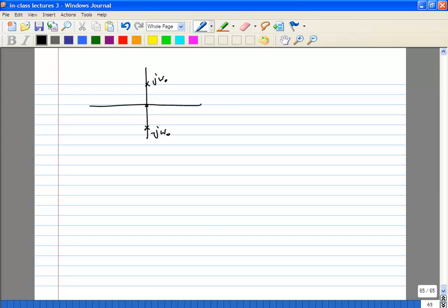So what happens is, initially the poles start off somewhere here in these two places, right? One of them is a capacitor, other is an inductor. Eventually they will move somewhere here. And you will see them splitting at some frequency. Actually, this is your Q equals half point. That is a point where, if you take your discriminant, root of b square minus 4ac, you will find that at that point it goes negative, and you can get this condition Q equals half from there.